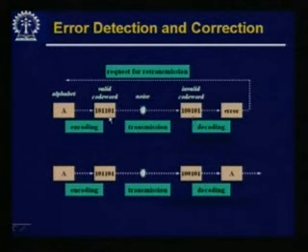But if I can correct a single error on the other side, then I do not need to ask for retransmission. Naturally, overall my efficiency may improve, but of course for error correction I have to send more bits. So, that is one area where I am losing something also. It all depends on how you do your engineering and how you come to your particular point of optimal amount of error correction.